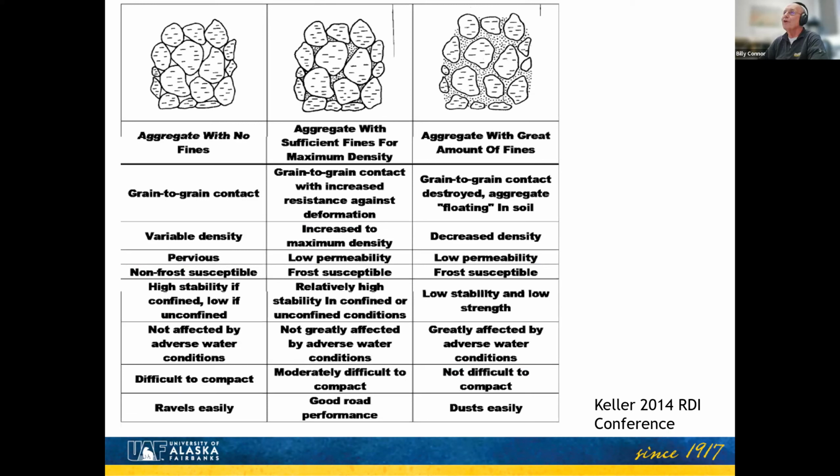On the left, we see the aggregate with no fines in it, and all of these voids are created. So you end up with just gravel on the surface, and that's not holding up very well. In an ideal world, if you get everything just right, you're going to fill all of those voids with a fine grained, graded material, and that's going to, in effect, glue all of that together. But we don't want to separate that coarse aggregate, because that's what's going to carry the load of the traffic.